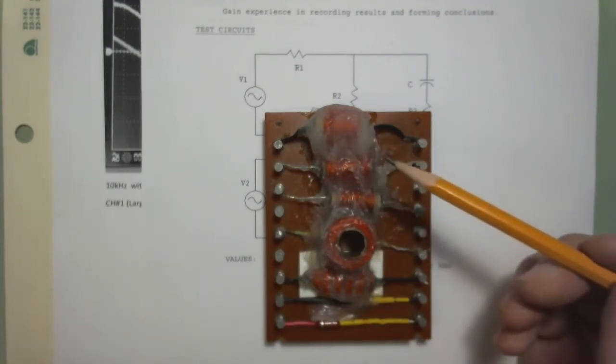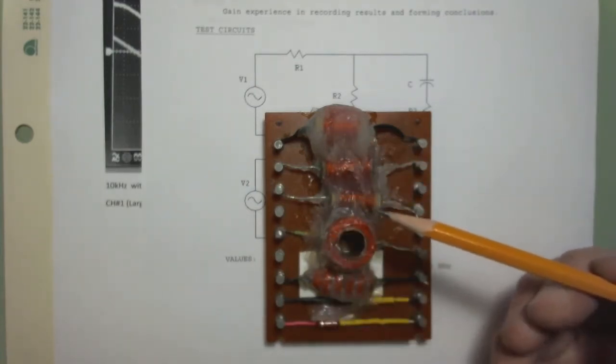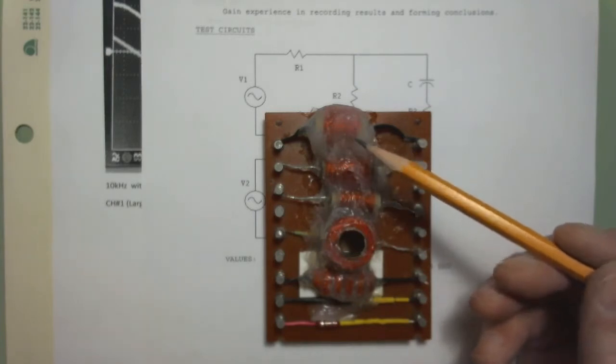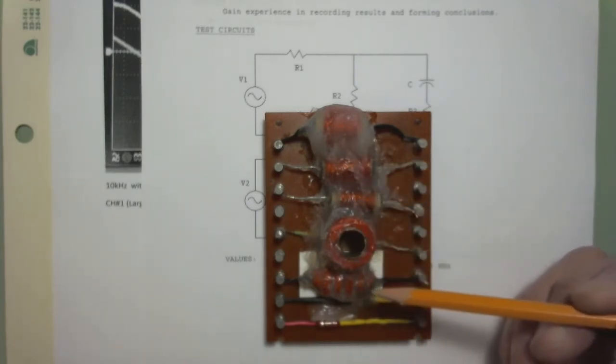It's very thin wire, so they can be damaged, so we usually try and put them on something so that they don't rattle around in the drawers and whatnot and get hurt. This was the 500 millihenry one that we used last time. This has an air core. Most of these are steel core. And this is the 2.5 millihenry that we're going to be using this time.